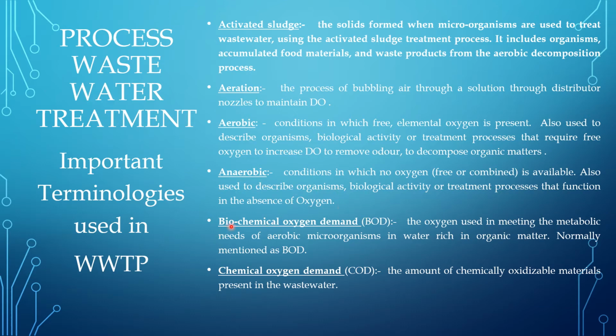process. Biochemical oxygen demand or biological oxygen demand, BOD: the oxygen used in meeting the metabolic needs of aerobic microorganisms in water rich in organic matter, normally mentioned as BOD 5, because it will take 5 days to test the BOD value. Chemical oxygen demand or COD: the amount of chemically oxidizable material present in the wastewater is called chemical oxygen demand.